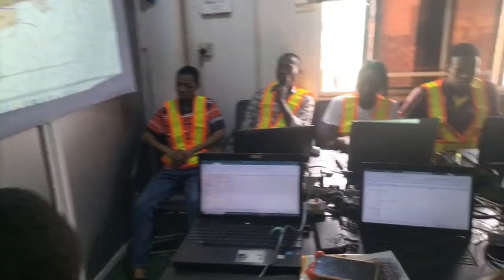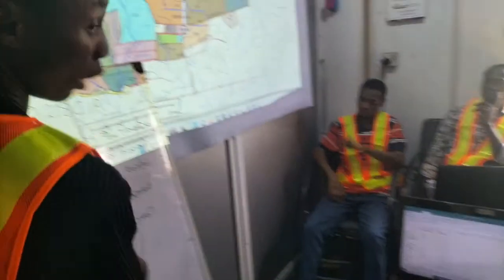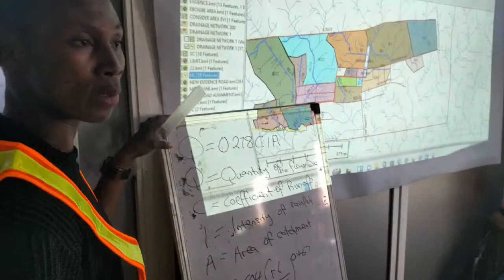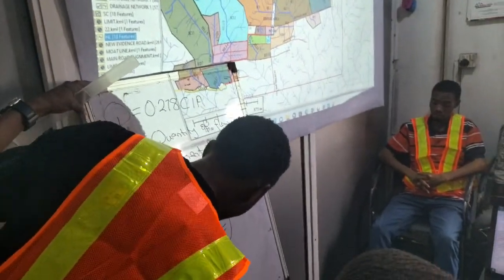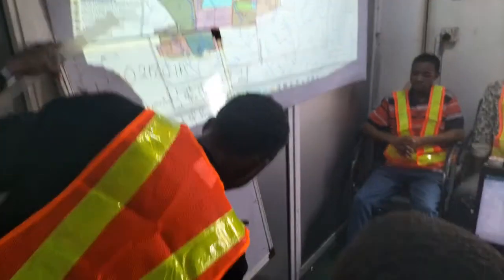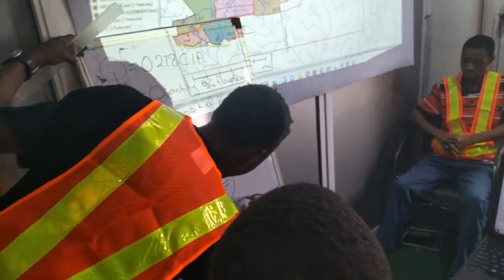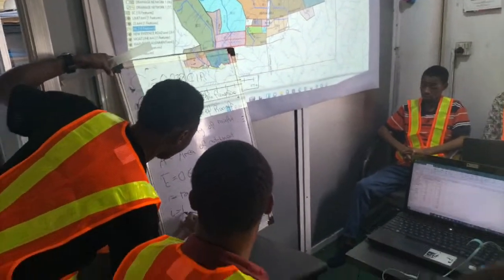We have our Tc, the time of concentration, is 0.604 (RL over root S) raised to power 0.467. Our R, like we said, is roughness coefficient. Our L is the hydraulic length.